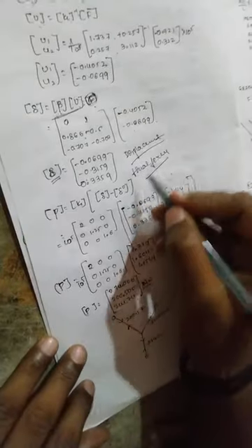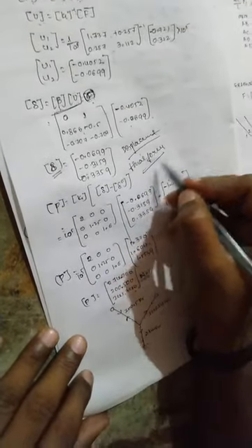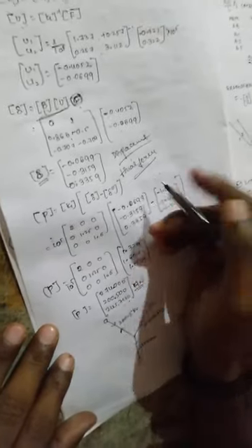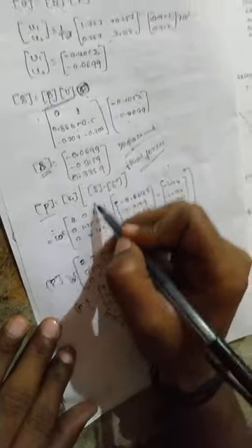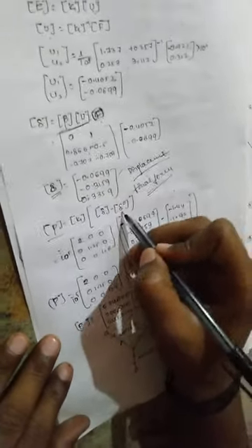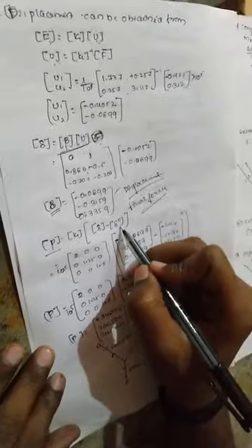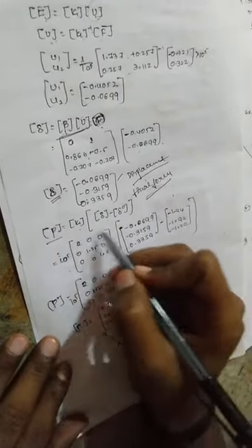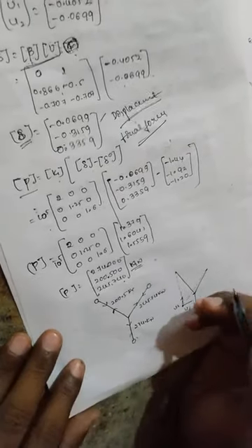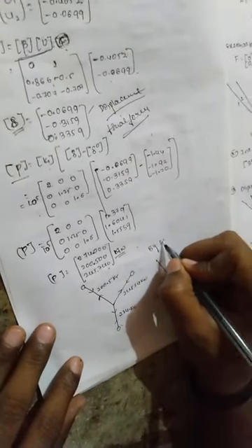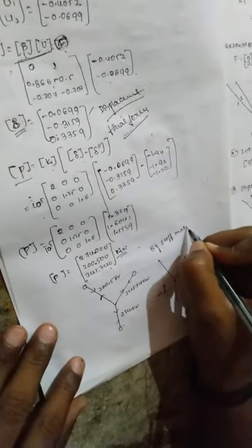Now once you find the displacement, you have to find the final forces, the member forces. My final force P is equal to K into delta, whatever delta we found here, along with the delta naught we found before. So we put in that K value and substitute all the values, and we get the P value. The final P value we find is the member force applied on each member by the stiffness matrix method, or the stiffness method.